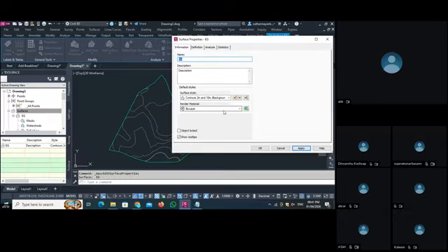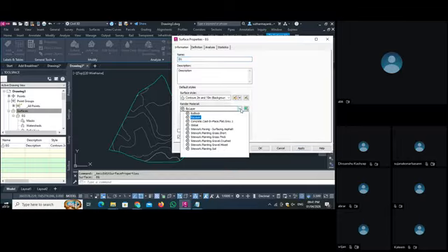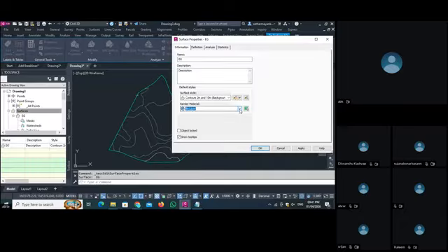So this is the render material. This render material we can use as default. But if the company is working in a modeling part, they have their own render material too. If you have a template, you can use the render material with the help of the template. Even Civil 3D provides some render material for different types of work. You can use it if it is workable for you. The same way we edit the points, we can edit this contour from here. So we can create a new surface style.